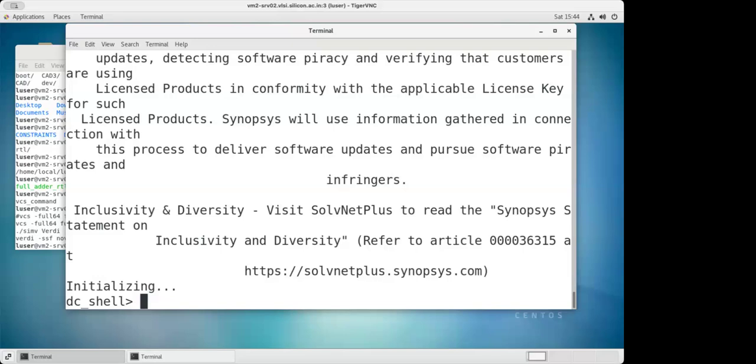You're supposed to be inside the DC folder first. All of you are able to see this dc_shell. Now here we will do a couple of things. Run the file, source the file, and after that we will type certain commands. I can show you what is there and how it is going to change. Once you get this DC shell, do start_gui. I will show you the GUI portion also. start_gui.